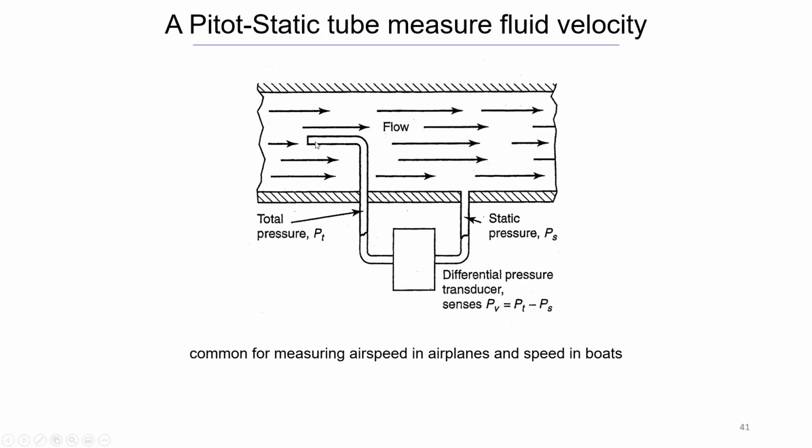In this case here, though, we're taking the velocity and we're redirecting that down. So this here is also going to be that dynamic pressure. So it's the total pressure since it's both of those. And then at this point here, if we took the total pressure and we subtract the static pressure, we can just get the velocity pressure.